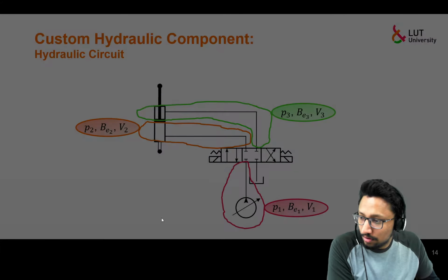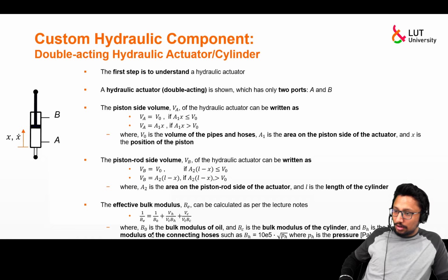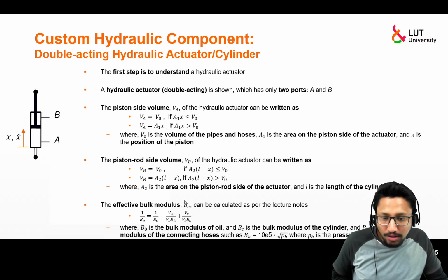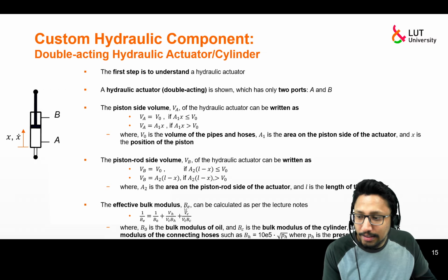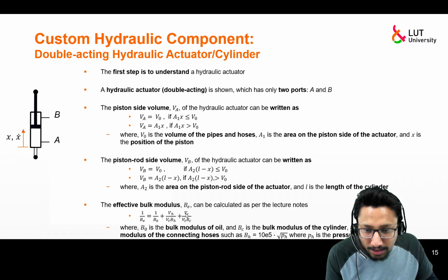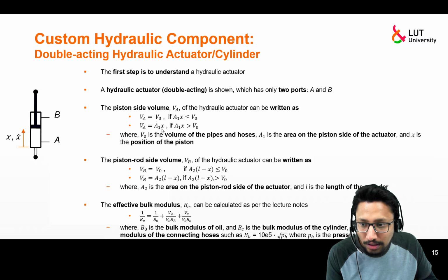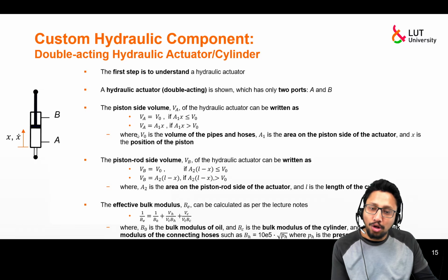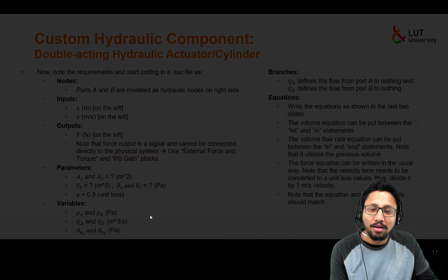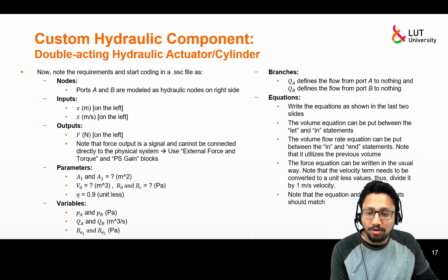If you see this equation here, it is changing with time. The reason is that they depend on the pressure, or the volumes depend on the piston position, and the piston position is changing with time, so the volumes and the effective bulk modulus are also changing with time. For that reason they are also variables.